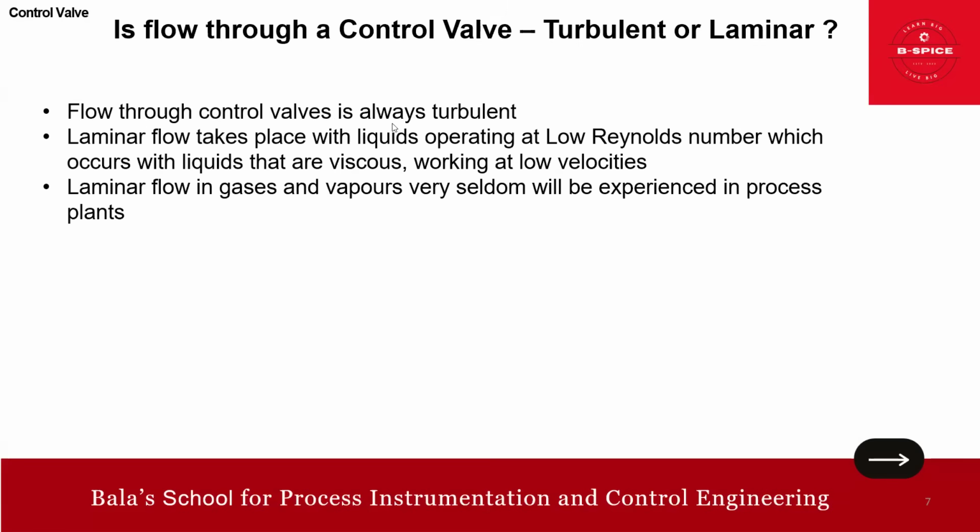Of course, flow through a control valve is always turbulent. Laminar flow takes place with liquids operating at low Reynolds number, which occurs with liquids that are viscous and working at low velocity. Just remember, friends, flow through a control valve is always turbulent.